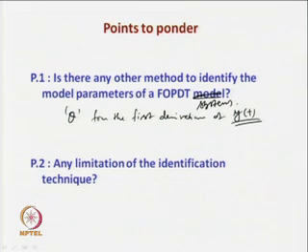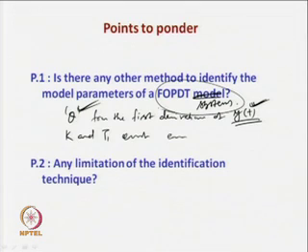When there is a large change or a discontinuity in the output, the time taken to that point from any zero crossing can be taken as the time delay of that system. Then the remaining 2 parameters k and T1 can be estimated using any 2 expressions we have derived earlier. So, there are other techniques also to identify the model parameters of first order plus dead time systems or higher order systems in terms of first order plus dead time transfer function models.